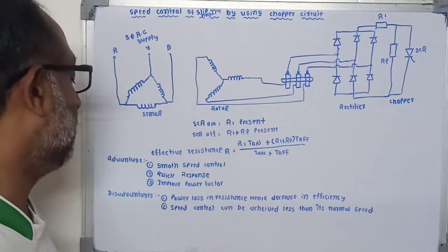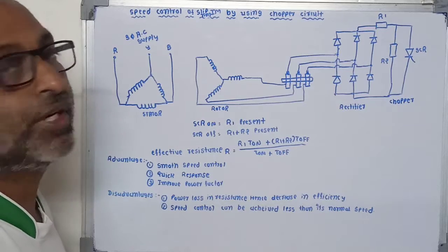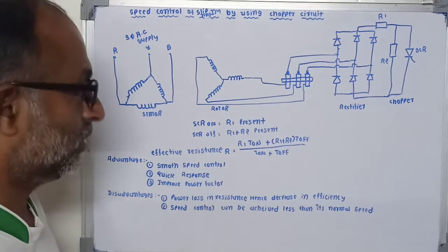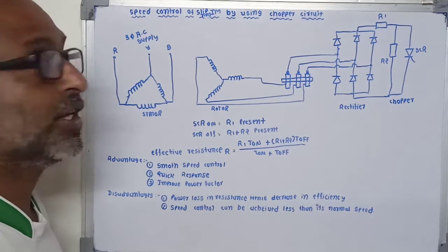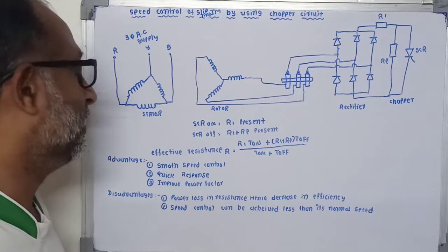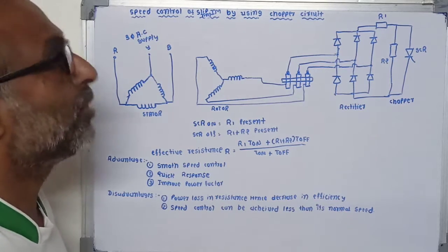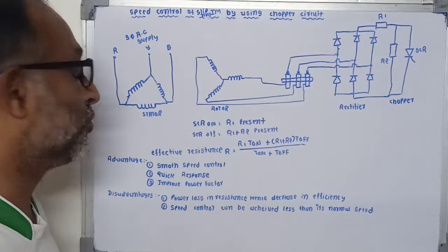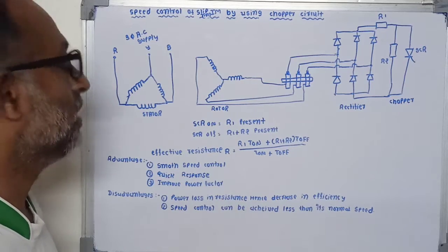So there are some advantages. First, smooth speed control can be achieved. Its response is very high, and it also improves the power factor of this induction motor. It is the most important advantage of this method.